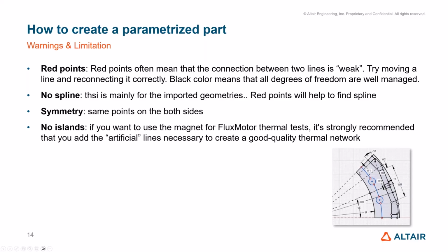This is not a specific law. I mean, it happens that red points can also allow you to create your part, but it is something that we have to check, especially with the spline. It is mainly for imported geometries, and normally you will see a lot of red points along the spline. This means that you have to rebuild the line.